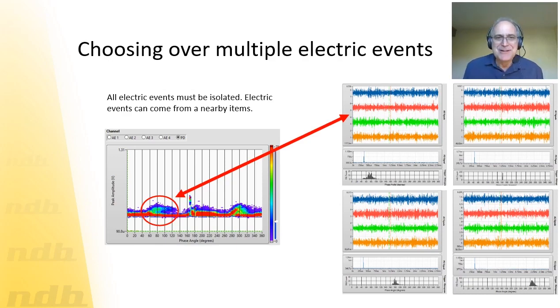So the thing is, electric can capture all the surroundings in the substation, all the surrounding electromagnetic emission that can also come from a defective lightning arrestor or defective bushing and other accessories. So the arcing produced by something else will generate electromagnetic emission, and your transformer will act like an antenna and receive this energy, and it will flow to ground, and you will measure it. And this is what happened.